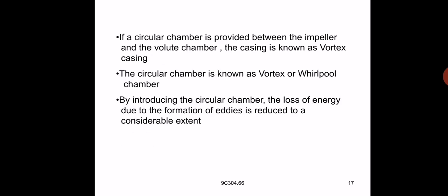By providing the circular chamber, the loss of energy due to the formation of eddies is reduced to a considerable extent. Hence, the efficiency is more when we use the vortex casing in a pump, compared with the volute casing.